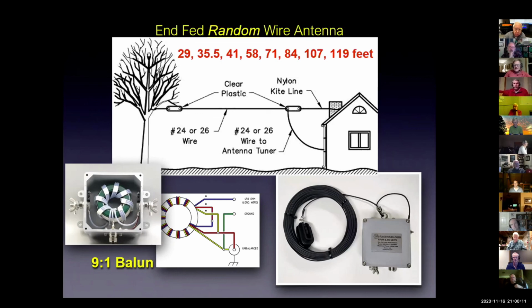Now, having said that, I don't spend a lot of time tuning antennas. I put the tuner on and live with it. But especially if you're doing QRP stuff, the hardcore guys will tell you if they can get an antenna that's truly resonant at a particular frequency, they're going to make contacts they don't make with a tuned antenna. Okay, for what it's worth.